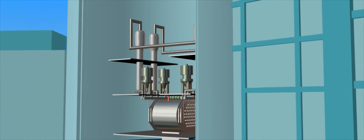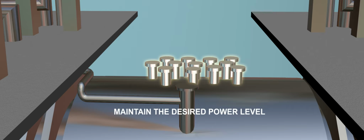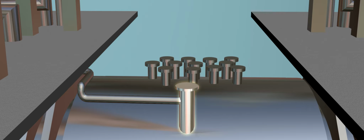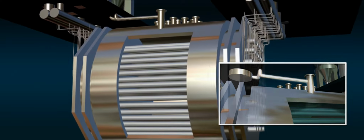Now, let us go back to the nuclear power plant to know about the safety systems. Back in the calandria and the reactor building, there are 2 important systems for safe shutdown of a reactor: shut-off rods and the secondary shutdown system. The control rods are used to maintain the desired power level of the reactor during operation and to shut down the reactors when fully inserted. The secondary shutdown system, which is based on addition of neutron absorber into the moderator, helps to bring the reactor to safe shutdown during normal and emergency situations.